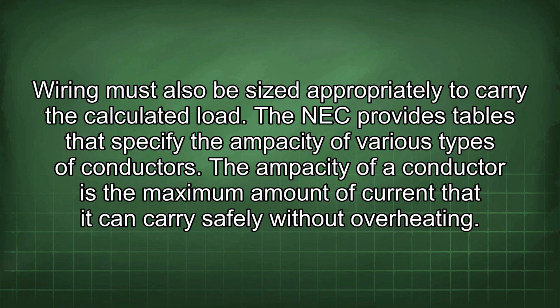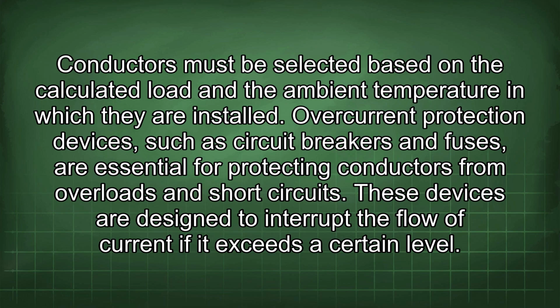The ampacity of a conductor is the maximum amount of current that it can carry safely without overheating. Conductors must be selected based on the calculated load and the ambient temperature in which they are installed.